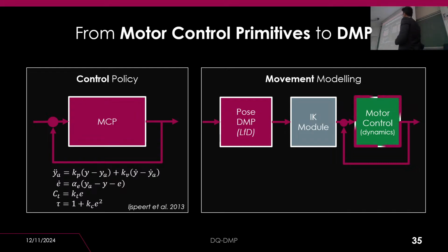Here you have your DMP. So the output of the DMP. What do you have from the output of the DMP there? Oh yeah. So the output of the DMP is the end effector pose or the end effector trajectory over time, the position and orientation in the workspace. Yeah. After that you have the inverse module that produces the position of the articulations. Yes. Okay? And after that you have a position control.